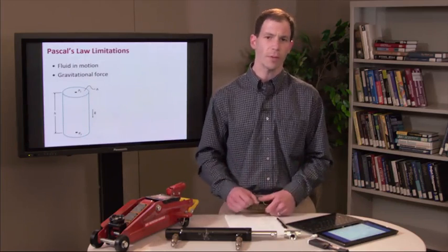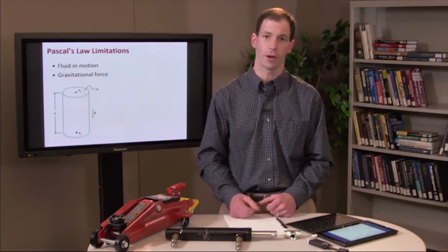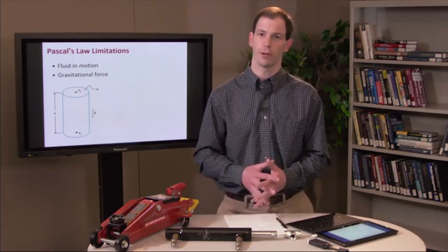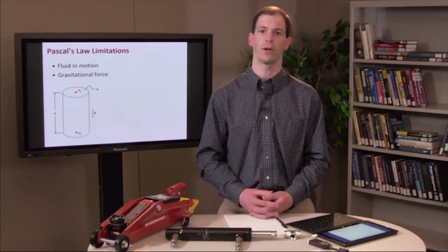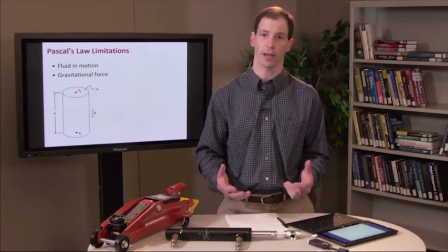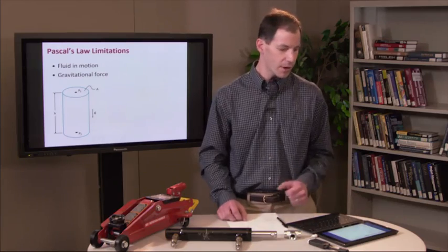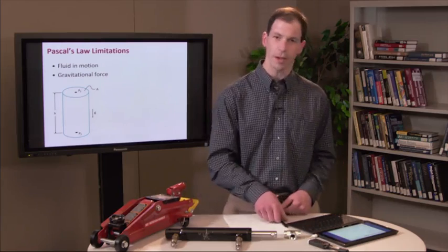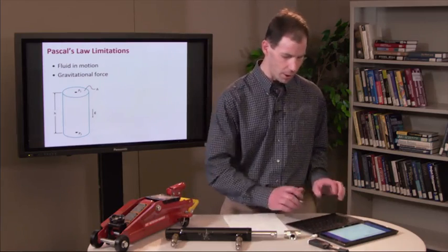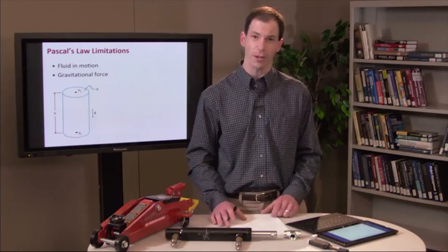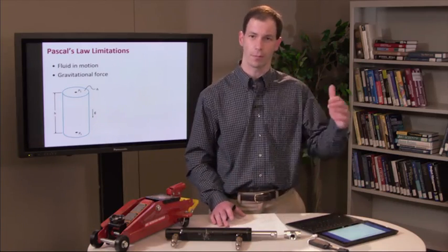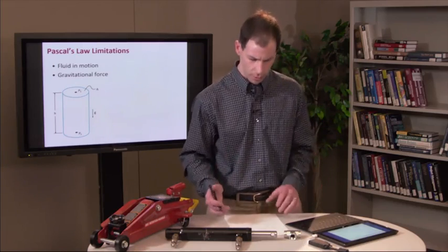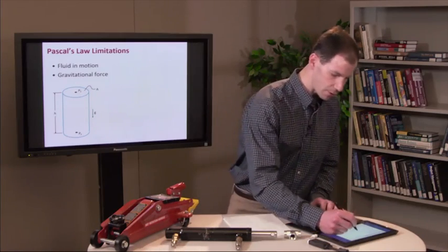So two limitations I want to highlight here of Pascal's law that we're going to address later in the class. The first is assuming that the fluid is not in motion, which means that we don't have any viscous forces, we don't have any kinetic energy losses. And the second is that we're neglecting any gravitational force. So if I look at a vertical pipe like this one right here, and I ask what the pressure relationship is as I'm moving up and down that fluid, and I assume that it's at rest, well, let me quickly do a force balance right here.